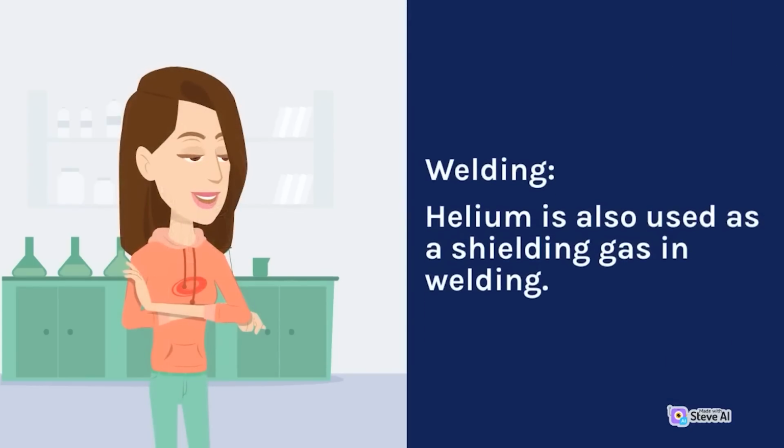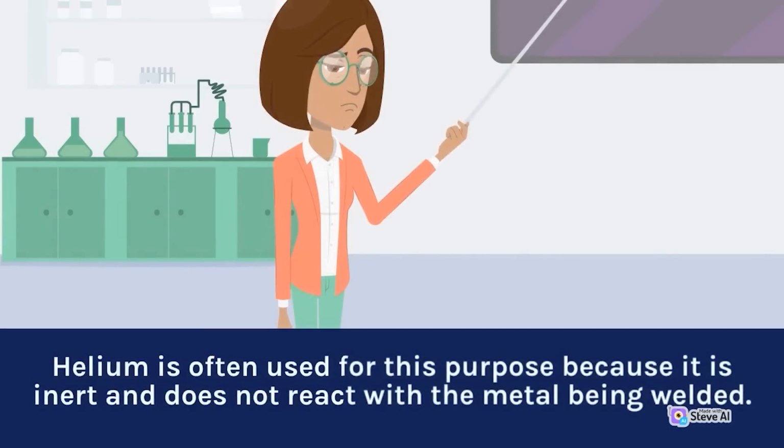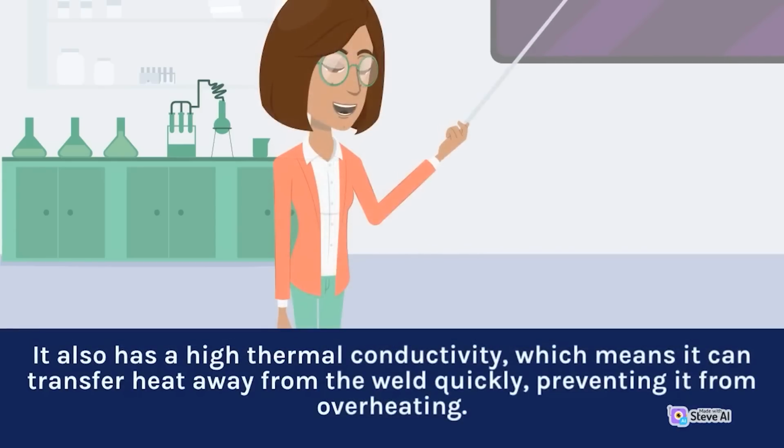Welding. Helium is also used as a shielding gas in welding. When welding, a gas is used to shield the weld from the surrounding air, which can contaminate the weld and cause defects. Helium is often used for this purpose because it is inert and does not react with the metal being welded. It also has a high thermal conductivity, which means it can transfer heat away from the weld quickly, preventing it from overheating.